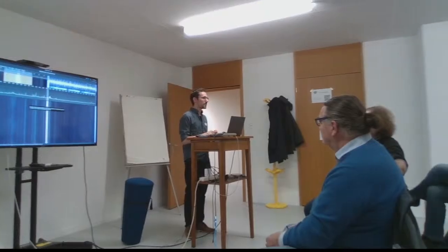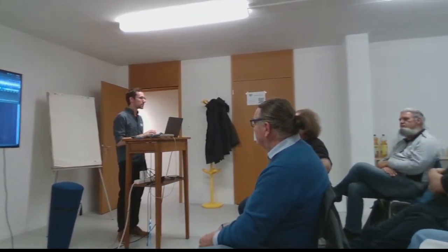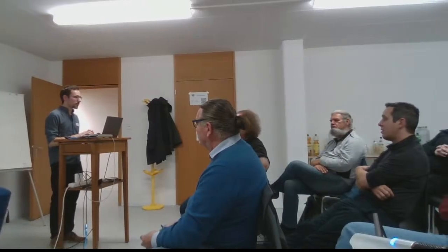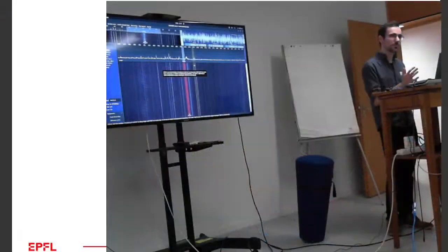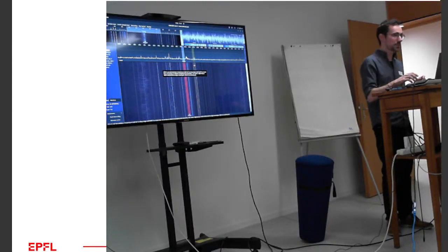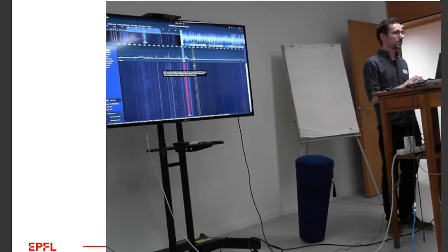Okay, medium wave? Which frequency range is it? It's in the 400 kilohertz range about, I would say. That one depends on the software-defined radio. There are some that go up to DC, so there is a direct conversion, but most of them would have a minimum frequency of maybe a few megahertz. So here, that one cannot go that low. Okay. But you can go to 433 megahertz. Yes, that one can, up to maybe 6 gigahertz.